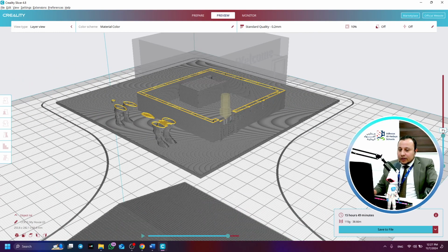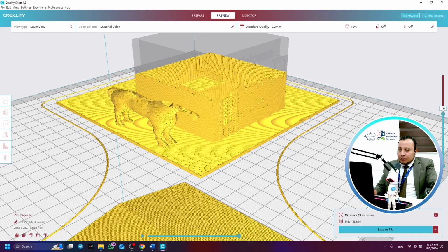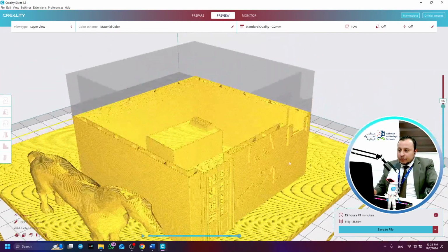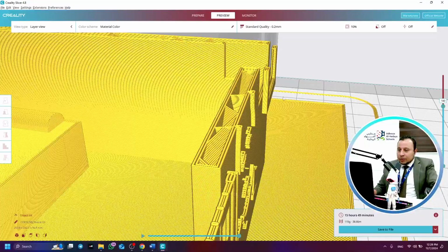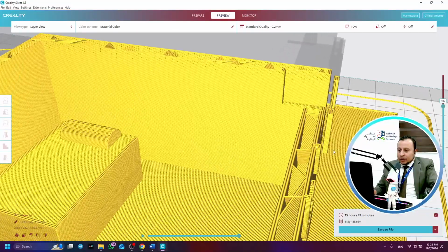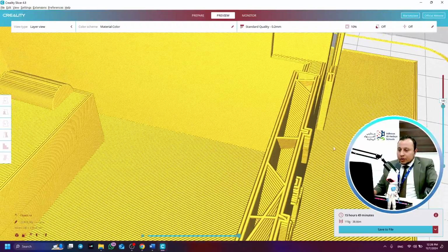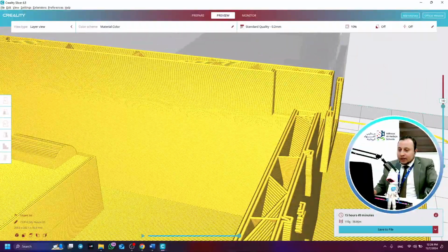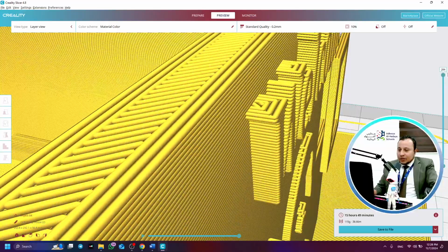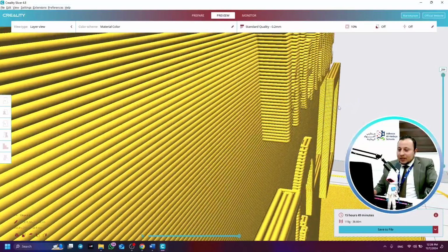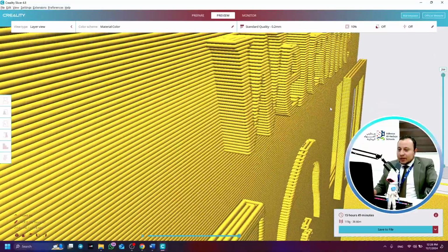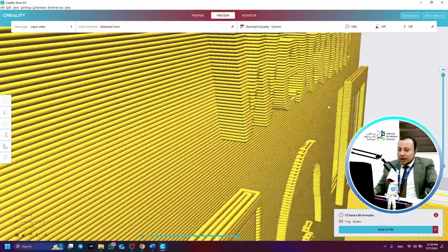What are the other areas here also? So let's say, maybe the window edge, the edge underneath the window. But this can go well, actually. You see that we already have a gap between the window and the wall. That's why I told you guys, try to make sure on Tinkercad that everything is stuck well together, because after printing, actually this window will fall down to the floor. You see? Number one, there is nothing underneath, no support at all.